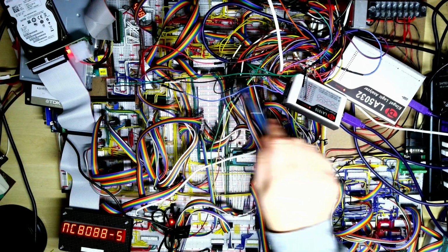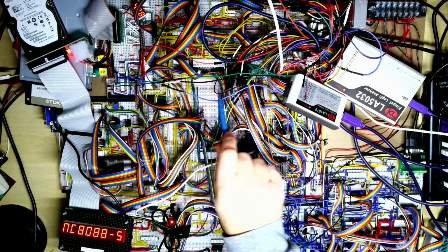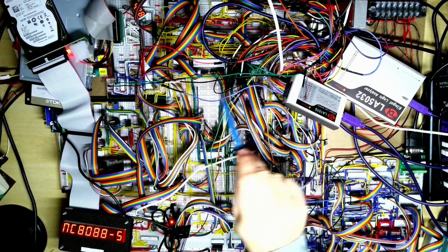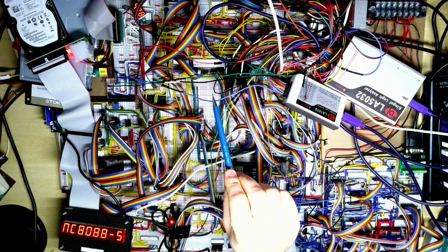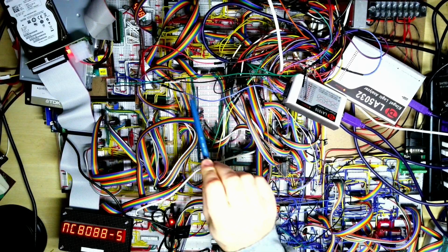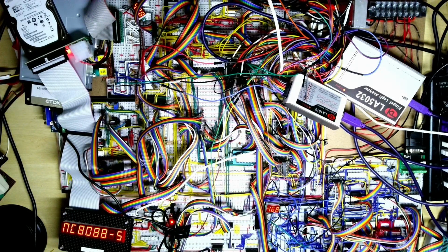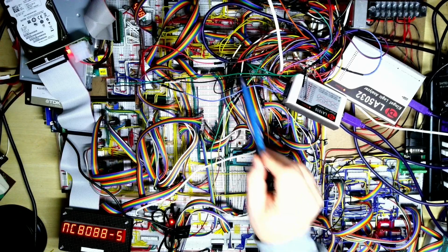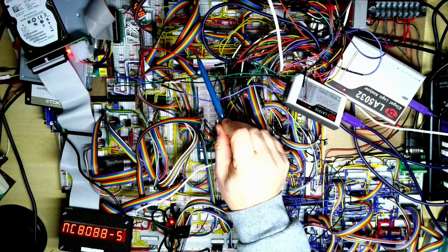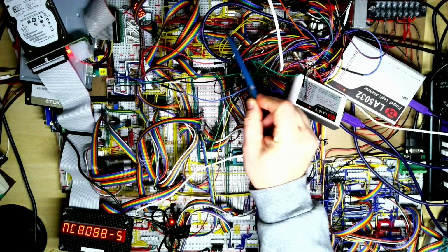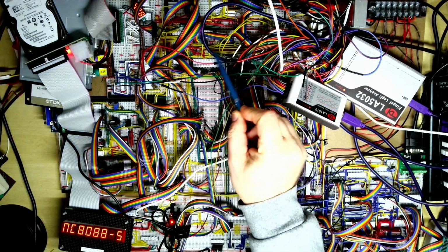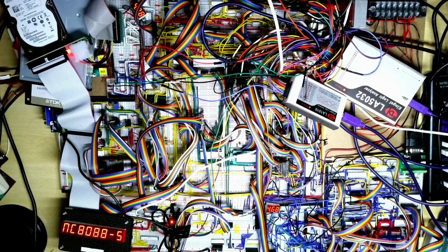Now at the top of the board up here, we've got the DMA controller and all its supporting logic. I'll be talking about the DMA controller in a minute, but the DMA caused an awful lot of trouble, and in fact the computer as it stands at the moment is not using DMA. We've also got interrupt controllers, system timer, and at the very top here we've got the power on self-test ports and a couple of the other ports which are needed for the base PC compatibility.